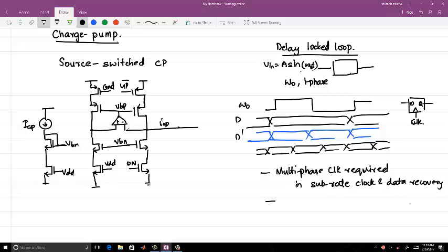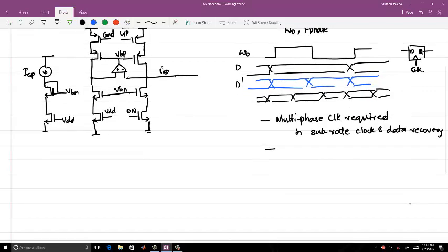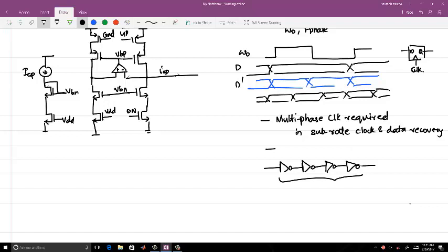But now just for an example, if I have this, this thing might not be good for your RF design, but it can be pretty good for your CDRs. So if I lock the delay of this loop, the delay of these four inverters, so TD of these four inverters is equal to one clock period, right? I don't need anything else. One clock period, I can generate multiple phases out.